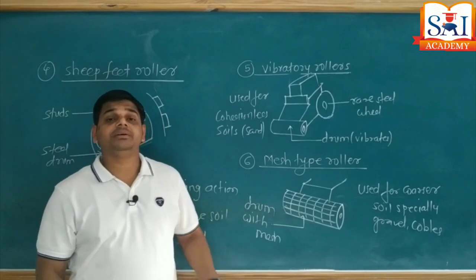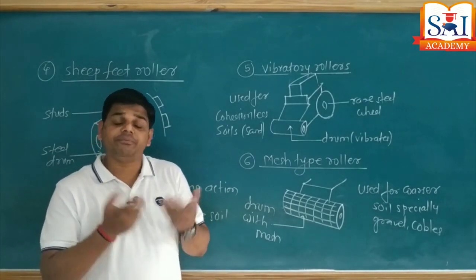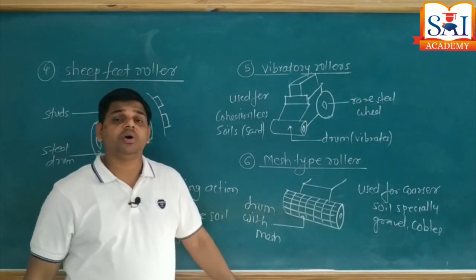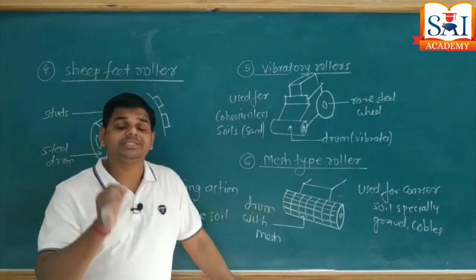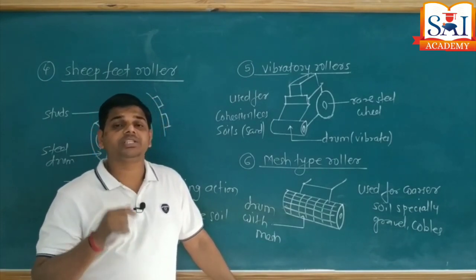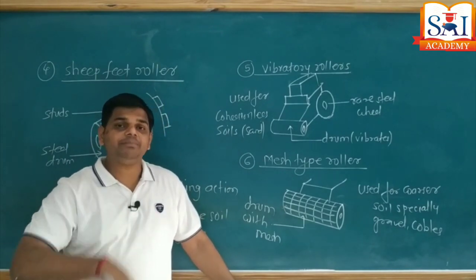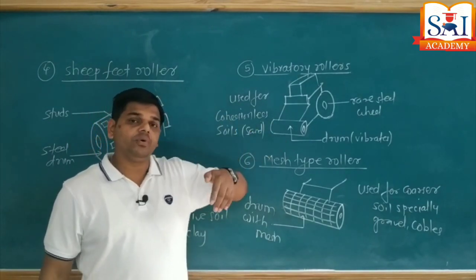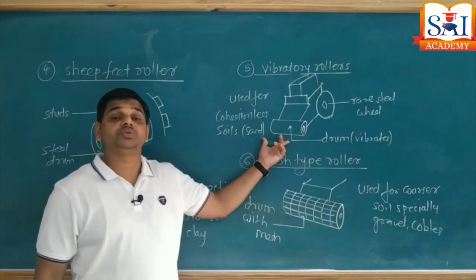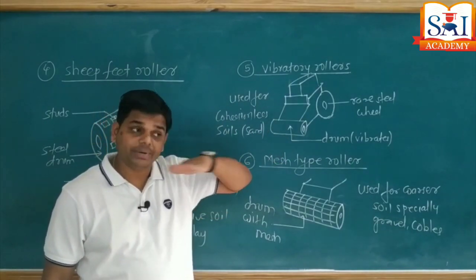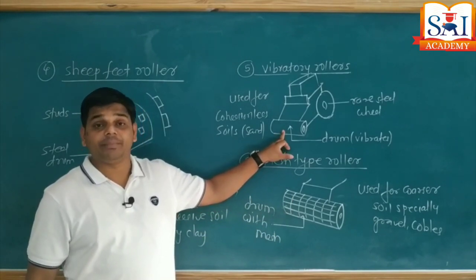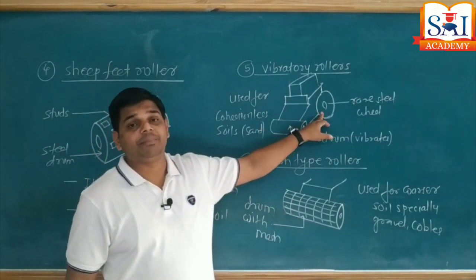In case there is sandy soil everywhere, even if we excavate to a far depth below, we will find the sandy nature of the soil. In that case, the foundation is constructed using the vibroflotation technique, and the vibroflot works on the principle of vibration. The same principle is in the roller, but the vibroflot goes deep inside to construct the foundation, whereas the roller provides a smooth surface or compacts the soil on the upper surface by introducing vibrations. So the front drum vibrates and the rear drum applies the pressure.